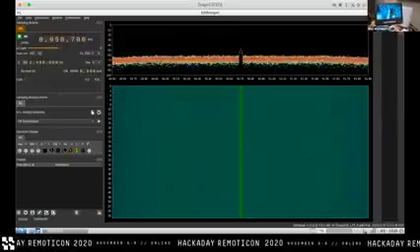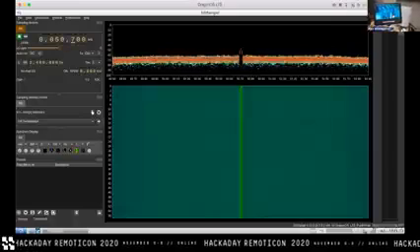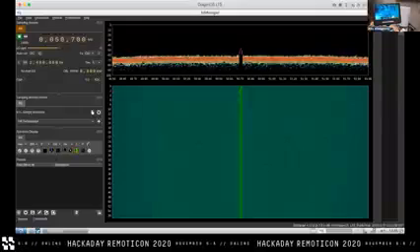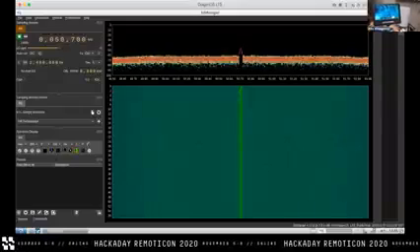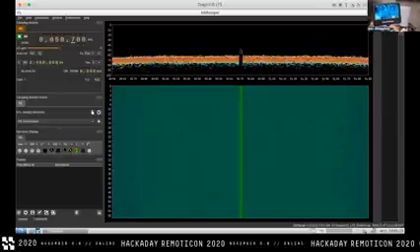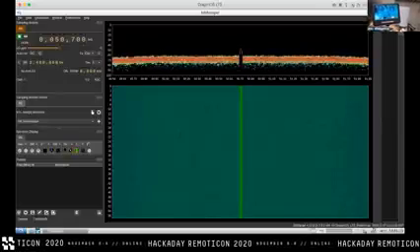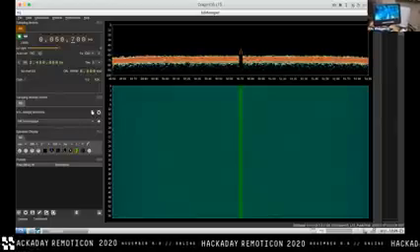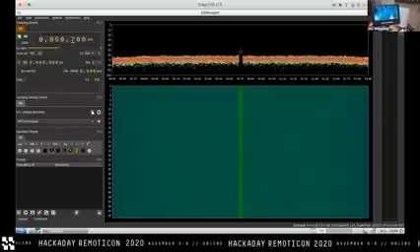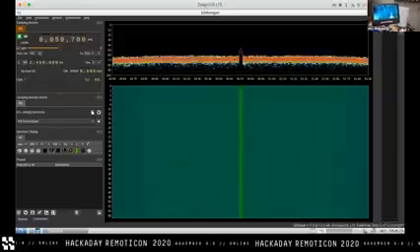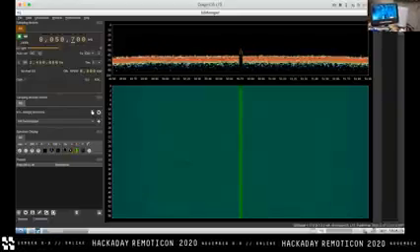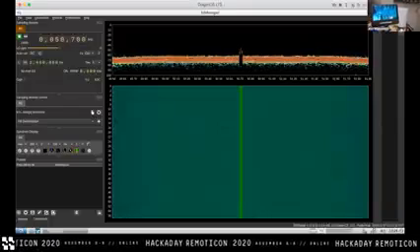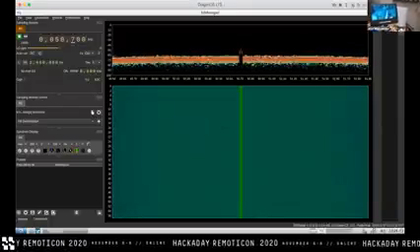probably coupling noise onto the IO bank supply rail because we're driving a relatively low impedance device at a ludicrously high frequency. This thing looks a bit like a capacitor as well as a resistor, as well as a diode. So we're really probably taxing that voltage rail pretty badly, and we're seeing it in the form of supply current from these capacitors trying to keep that rail stable. The other thing we might notice is this LED comes over here. Oh, I guess I wasn't even probing in the right place.